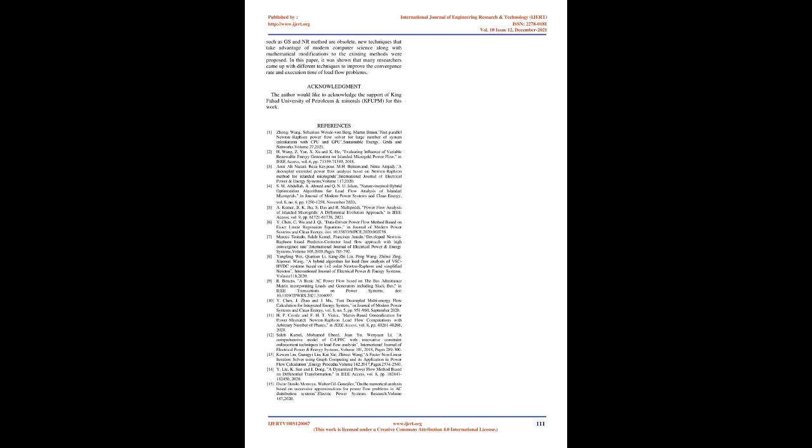The method was performed on IEEE 118 bus test system, 1500 node system of one province in China, and MatPower 10790 system. The proposed method was compared with MatPower. Even though the convergence criterion for the proposed method is 0.00025 and for MatPower is only 0.05, it was shown that the proposed method is 4 times faster.